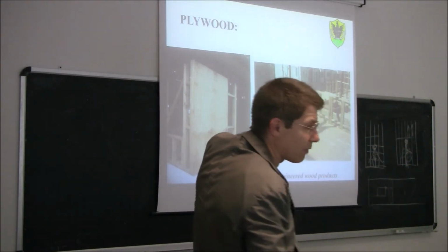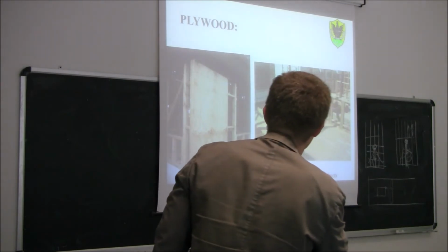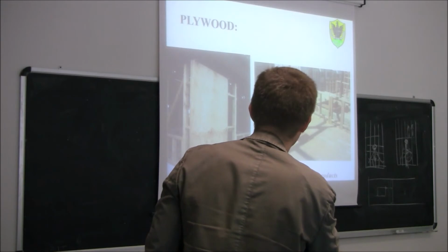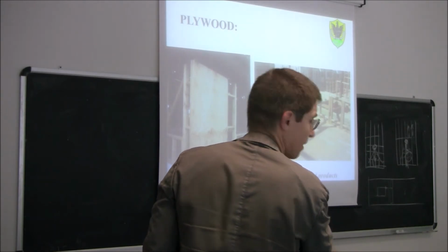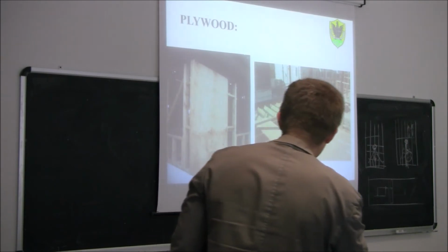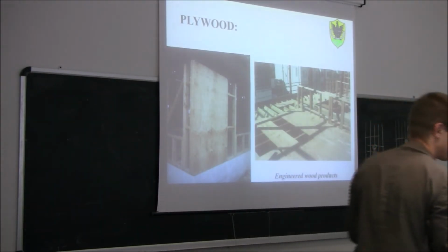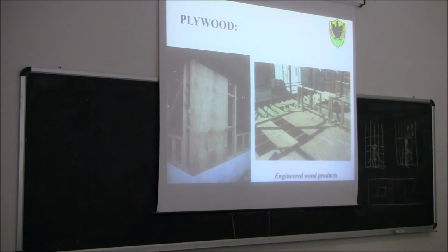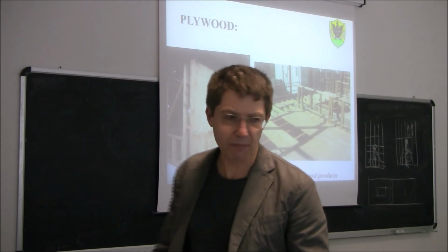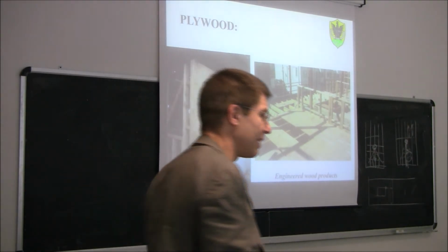On the inner side, you can't see, but on the inner side there is a frame. So you see there is a vertical stud in this way, there is a vertical stud here, there is another stud in between, and then there are some horizontal plates. So this sheathing of plywood is basically nailed on this frame in order to get this shear wall. This kind of construction system is called a light frame system. Sistema a telaio leggero.